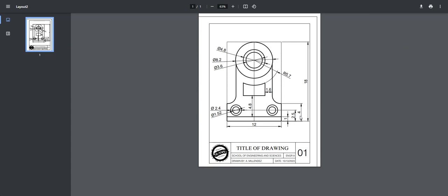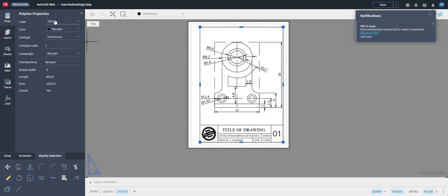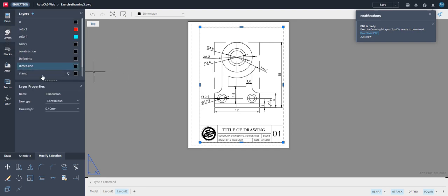The only thing I don't like here is that this margin here should be a little thicker. So let's work on that one. Work on making a thick border around here. So going back to our drawing, we know that this border, when I select that, the layer of this one is in T block. If you go to layer and select T block here, T block has a line width of 0.13 by default, and although this one is supposed to be in the correct layer, we don't want the line weight to be 0.13.